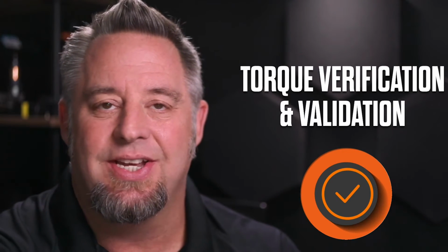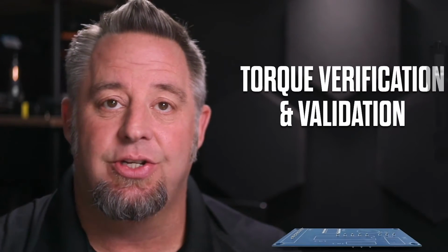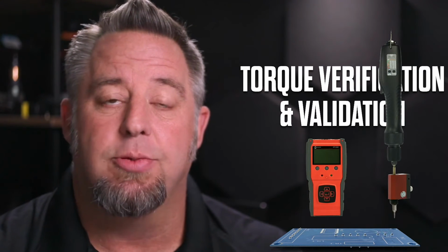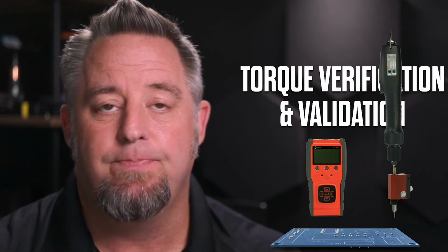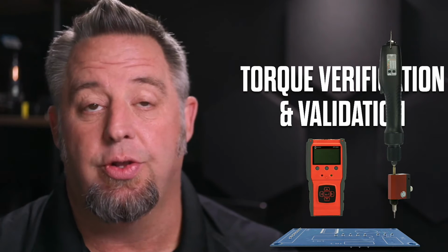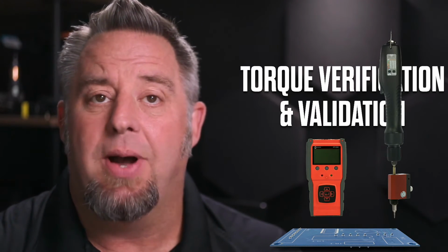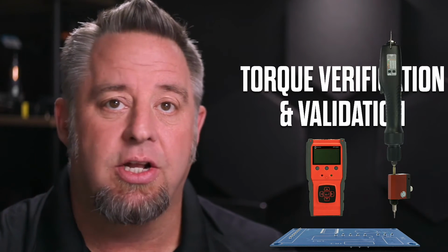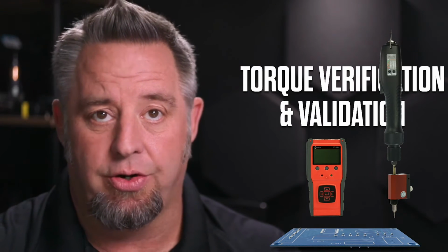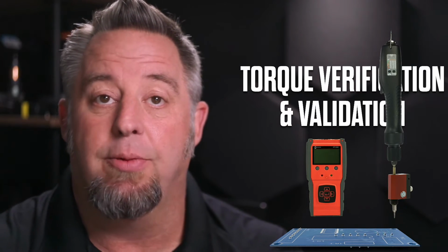And so the most accurate way for us to do this testing is by the use of a rotary sensor, putting that in between our application and our tool, and this is going to give us the actual torque that's being delivered onto the part, which is exactly what we want to see. So by this use, periodically we can not only confirm that the tool is performing correctly, but we are also delivering the torque value that we need for the part.